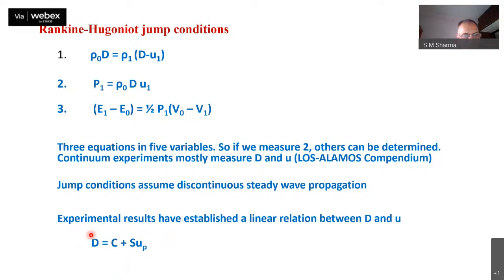For example, if a phase transformation does not take place, or if the material retains the same phase, then it will be a linear relationship. However, if the electronic structure or crystallographic structure changes, this linear relationship will break down. So these kinds of relationships have also been used to identify whether under shock compression the material is undergoing some fundamental changes.